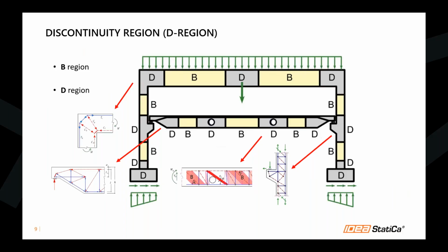So in this region, you cannot actually just use those formulas you find in the design code. You have to use another method, let's say the famous strut and tie, of course, you can use that. And yeah, some other approach that you can think of. But basically, it is a more complex process. You would need trial and error and so on.